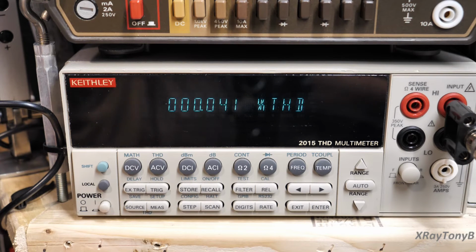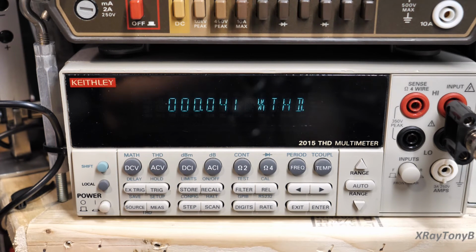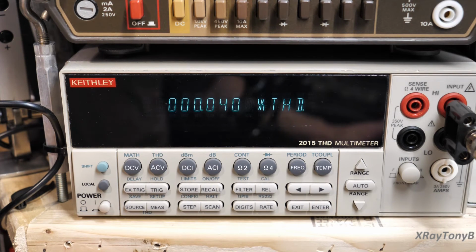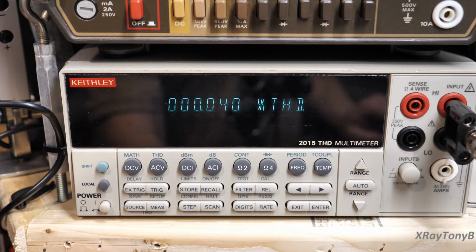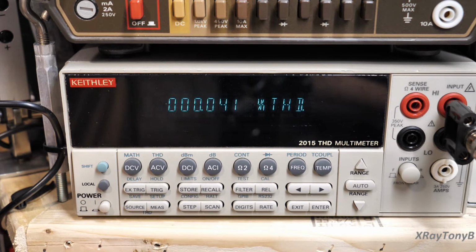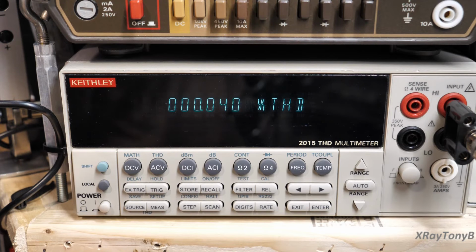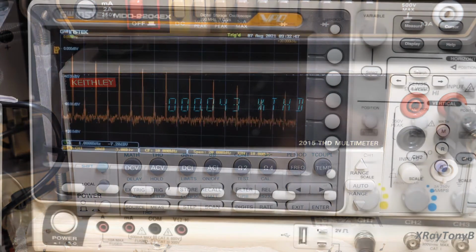So again, and by the way, the preamp is tracking very closely, because the first channel was 2.01 volts with that same input, and this one is 1.99 volts. So the gain of the preamp is very symmetrical between the two channels. So we know our power amplifier section, the two channels perform a little bit different with distortion, and they both exceed what they should be showing at rated power.